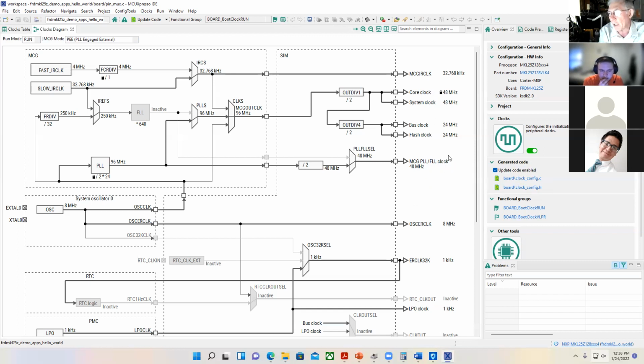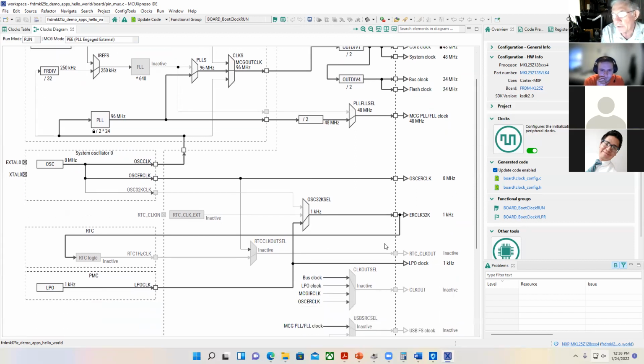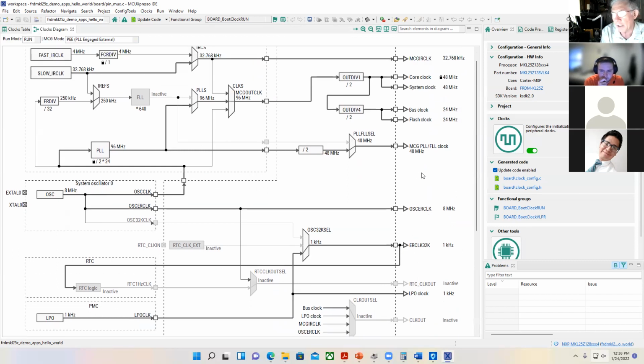And then these are some of the other clocks that come out. This is a 32768 hertz clock. That 32768 is a good real-time frequency, because it's easily divided by powers of 2 to give you a 1 second tick. And then some of these other clocks are distributed to some of the modules. But this is the main clock, and you can change the frequency, and this clock module gives you the ability to do that.